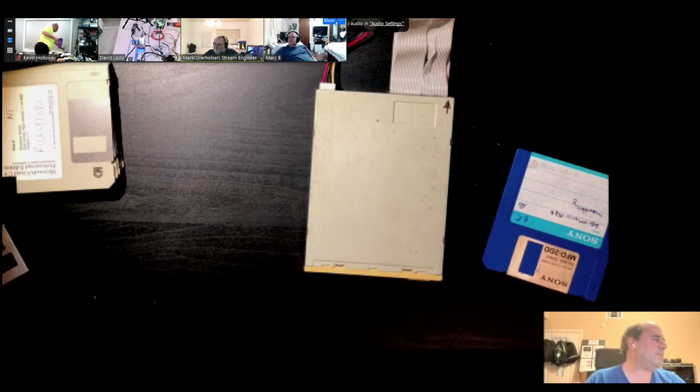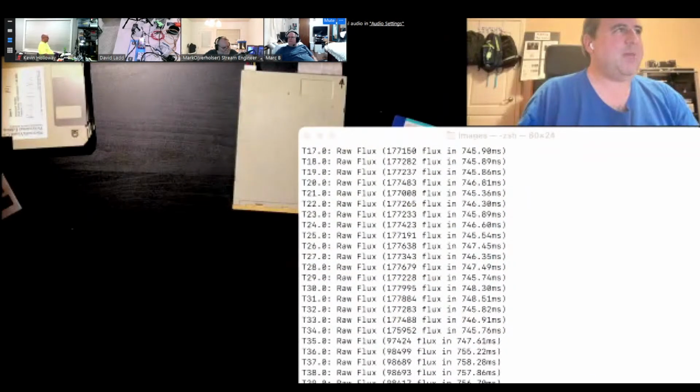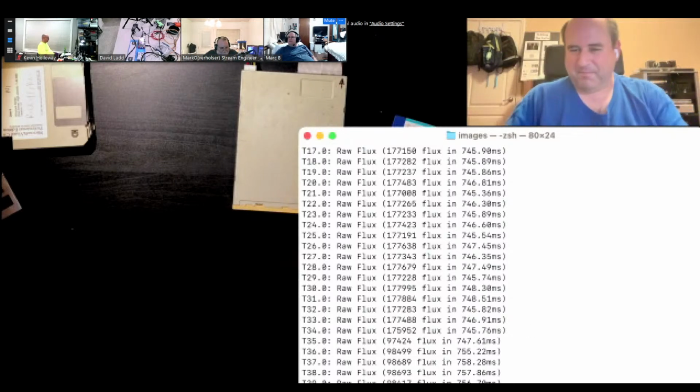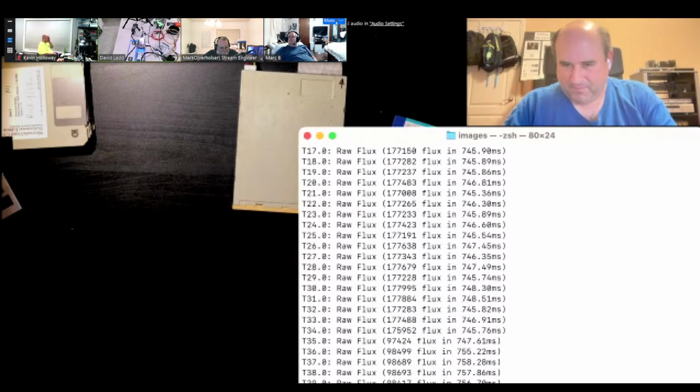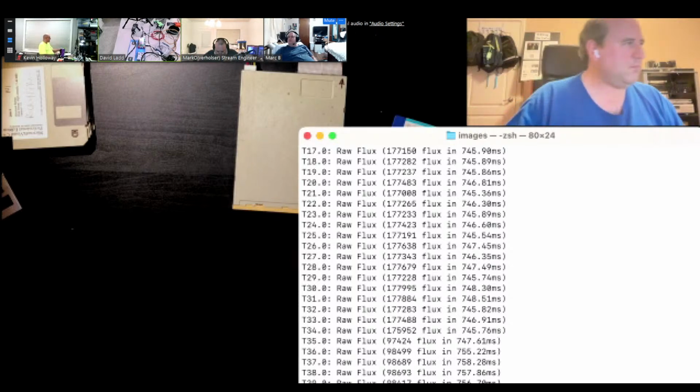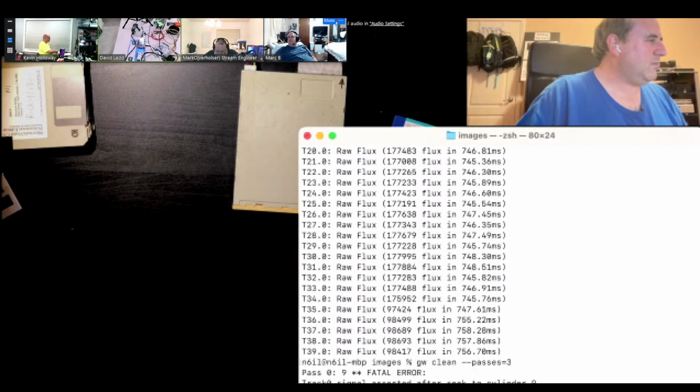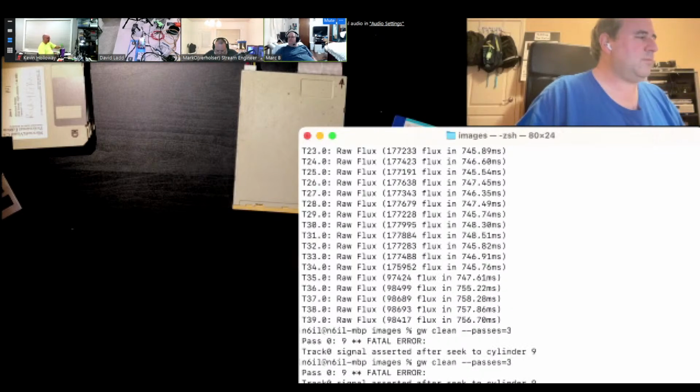And the density, number of sectors, I think the speed is the same, right? I believe the speed is the same. Yes, the 3.5-inch floppy drives for the CoCo and PCs are 300 RPM. Between the 1.4 and the 720s, and the 288s, they're all 300 RPM.